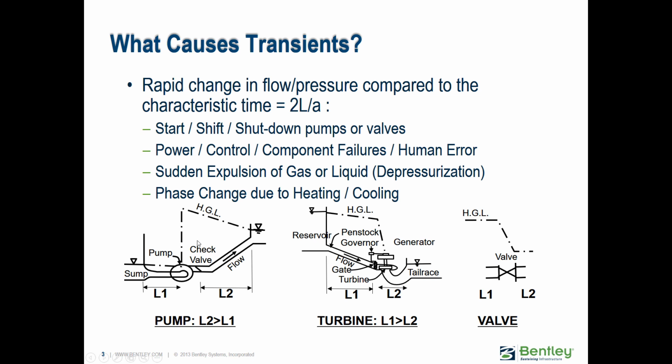But between those two steady conditions, you have a transient that may occur. Some other examples are something happening with a turbine. So maybe the electrical load is rejected, and suddenly the turbine is spinning up and you're closing a valve. Or maybe just a simple valve closure, which could be a valve to the atmosphere like a hydrant, or a valve between 2 pipes, or anything like that.